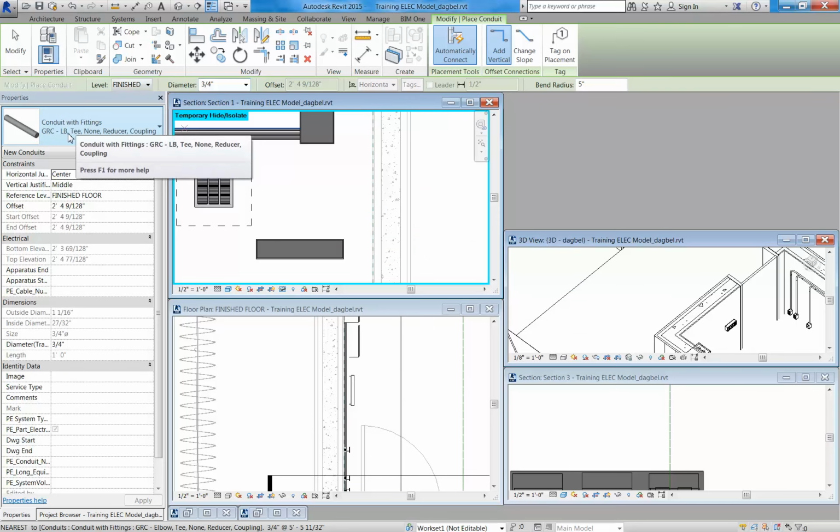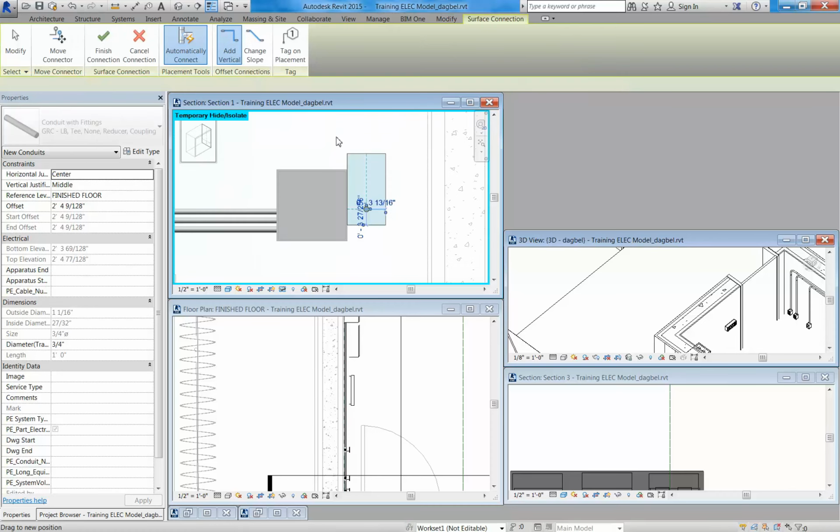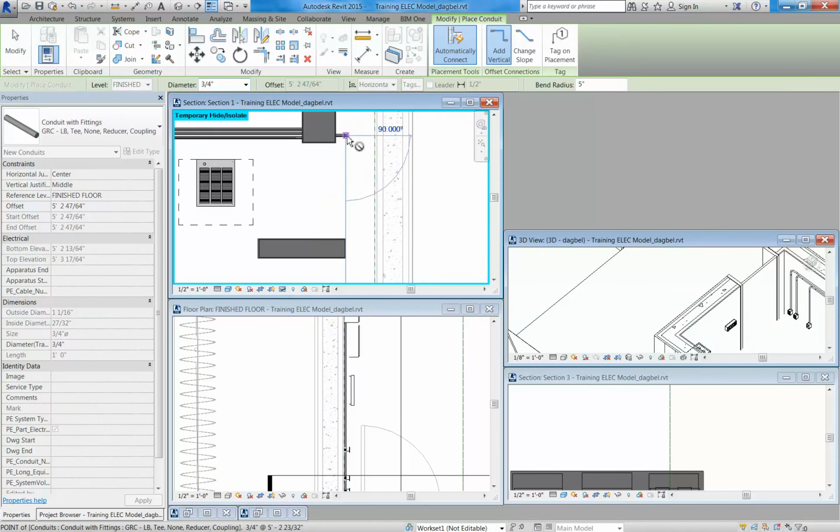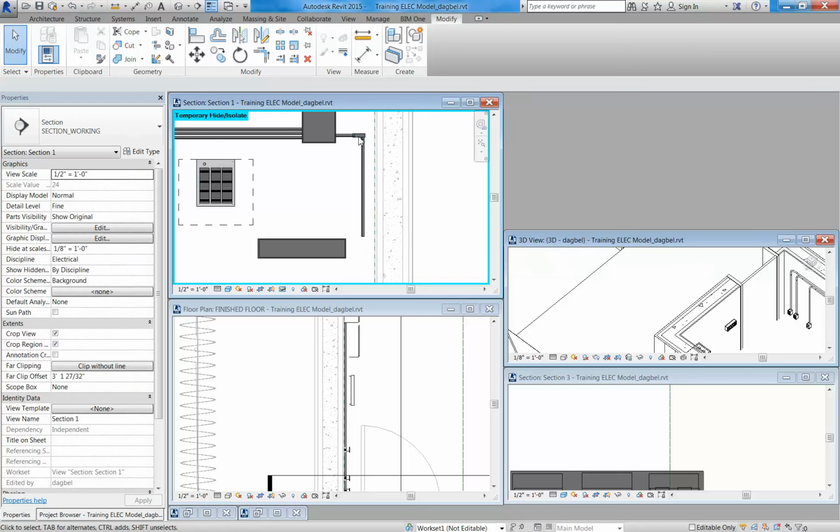And so now we see that we have an LB selected, so let's start here on this box. We can just finish that connection there, and we'll draw it out and bring it down, and notice it's got a cannot connect or cannot draw symbol because it says that we don't have enough room. So if we try to bring it out and then down, then it gives us the LB. But notice how it gave us this horizontal LB. That's probably not the one we want. We want a vertically oriented LB.